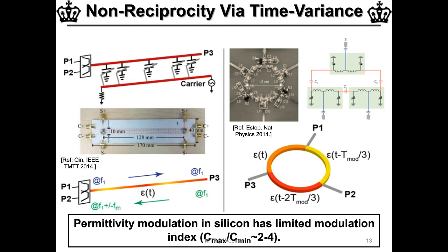Now, along the original transmission line, if you have a wave that's propagating in the same direction as the modulating wave, then it will pass through with a frequency shift, as is shown here, where the incoming frequency is shifted up and down by the modulation frequency, while a wave that's traveling in the opposite direction passes through the transmission line unchanged. And so now the direction of propagation of the wave has been converted into a frequency difference, and you can use duplexer filters to separate the forward and reverse traveling waves.